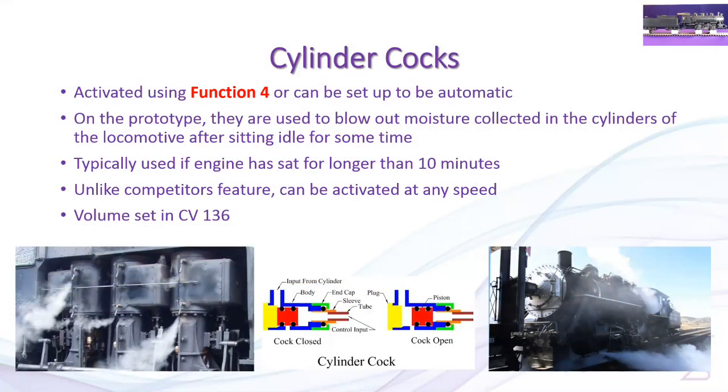So the next step is we're going to talk about the cylinder cocks. Now this is something new to Tsunami2 and Econami, and the cylinder cocks are a valve that usually sit at the bottom of the cylinder, and as steam condenses when the locomotive is stopped, it'll turn into water. And you don't want water because there's such little clearance between the cylinder head and the edge of the piston. Water doesn't compress the same way steam does, and so if water condenses, you can potentially blow the cylinder head off. So you want to make sure that you blow out any potential condensed water. So typically after the locomotive's been sitting for about 10 or 15 minutes or so, the engineer, to get going again, will then open the cylinder cocks. So let's go ahead and show that for you.